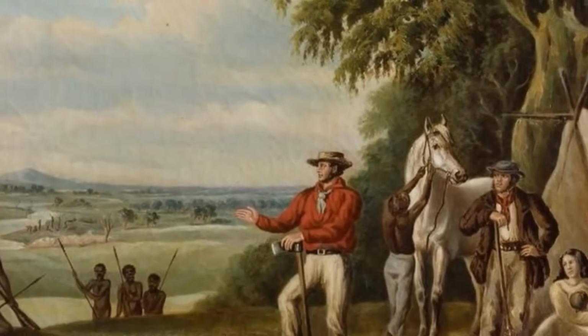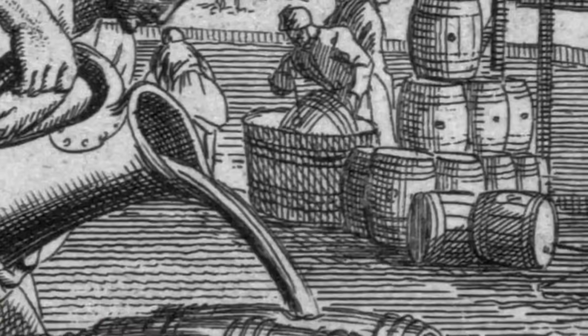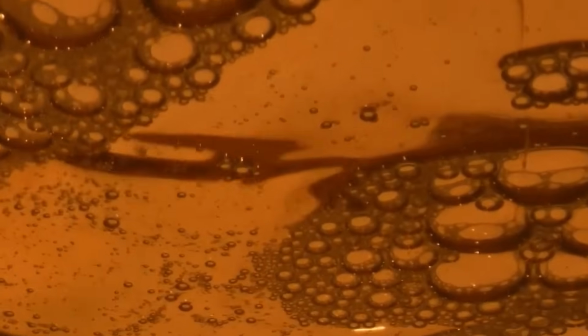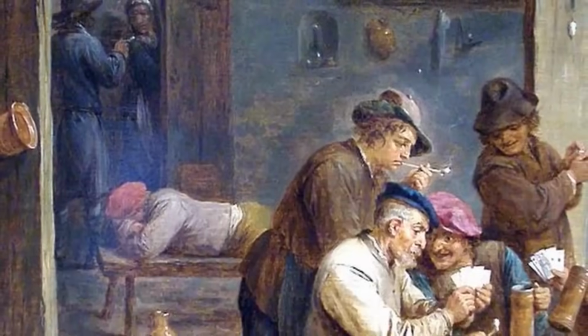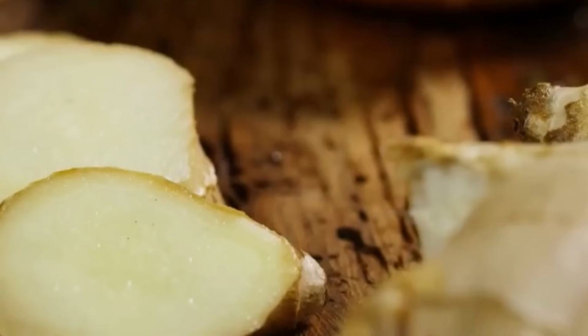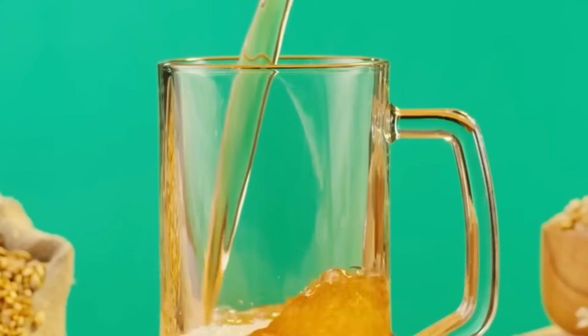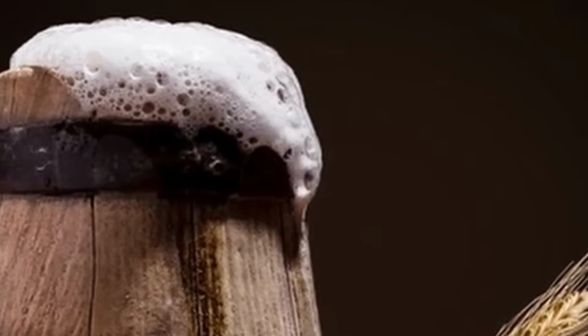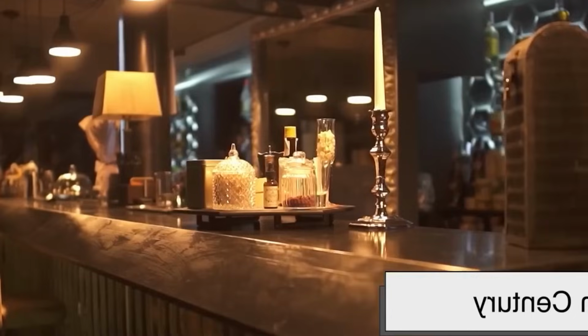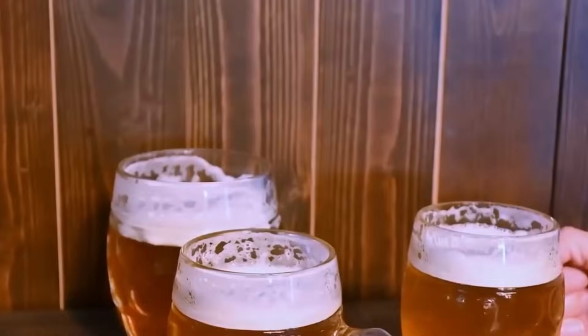Once stacking is complete, the pallet moves into an automatic stretch wrapper. Here, the pallet is spun on a turntable while a film carriage applies tensioned polyethylene film around the load. The film is heat-sealed at the end of the cycle, and the wrapped pallet is discharged to a staging conveyor.